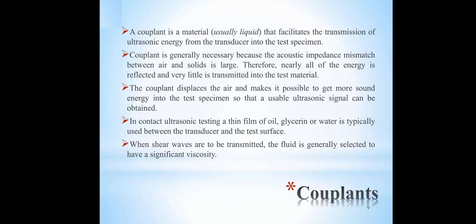Couplant. A couplant is a material, usually liquid, that facilitates the transmission of ultrasonic energy from the transducer into the test specimen. Couplant is generally necessary because the acoustic impedance mismatch between air and solid is large. Therefore, nearly all of the energy is reflected and very little is transmitted into the test material.